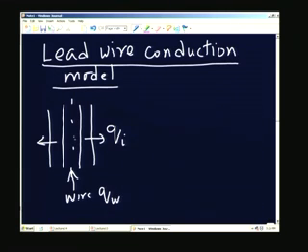So, we expect temperature variation to be in this direction predominantly, in the axial direction, and this gives rise to heat transfer like what is shown by the arrows. So, now the wire will conduct the heat axially, and some of the heat will leave through the insulation like this all along the wire, something like what is shown here, like a tree.